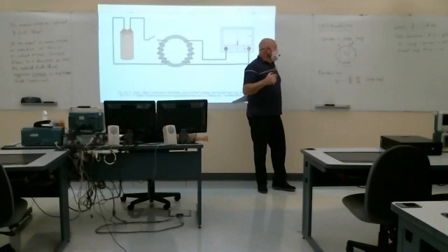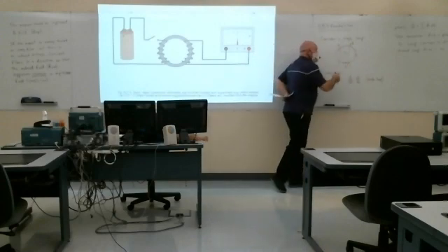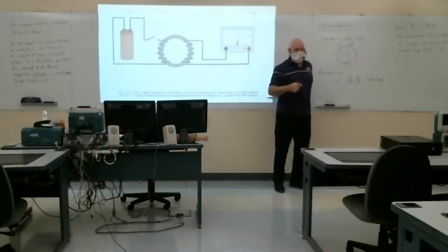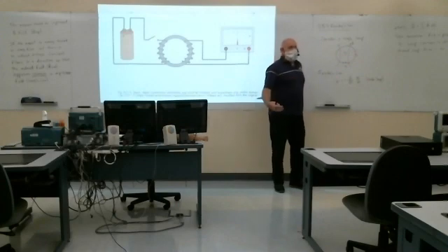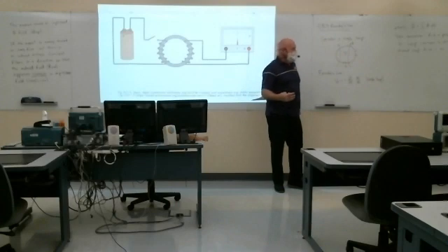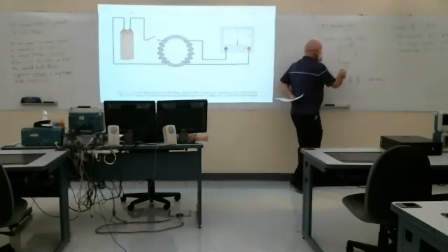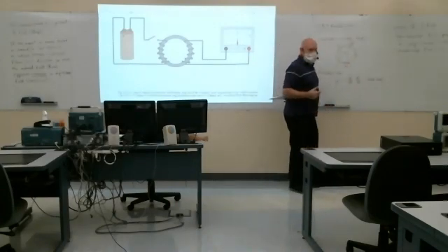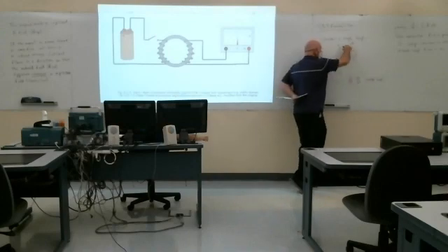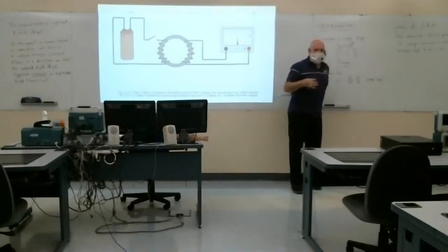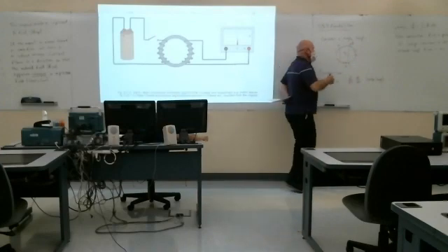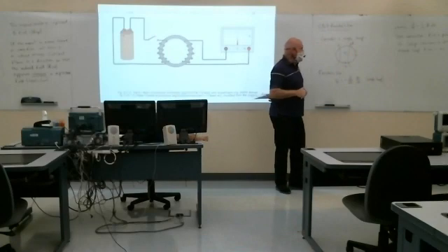Now, I say it in terms of the terminal voltage instead of the current, because if I don't have a resistor there, there's not going to be any current. But if it helps to think in terms of, well, what direction would the current be? You can certainly use that if you want to pretend that there's a resistor there even when there's not. But remember, the loop is like a generator. And the current comes out of the positive terminal of your generator.